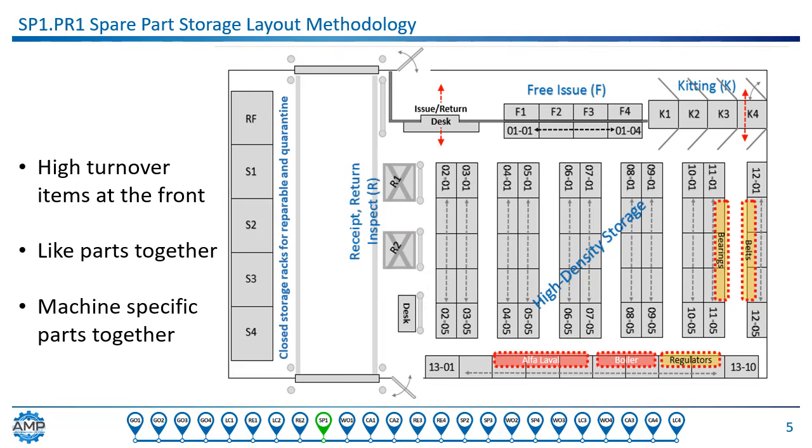The storage of parts can be centralized or decentralized. A mixed form of these storage methods is possible, and it's recommended that frequently used parts are stored locally near the point of use. Larger sites might find it beneficial to have satellite storage locations in the plant. This reduces travel time to and from the storeroom and can reduce unplanned downtime. They can also be used for consumables to help minimize spare parts being issued at the counter and traffic in the store area.